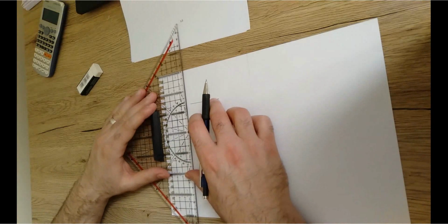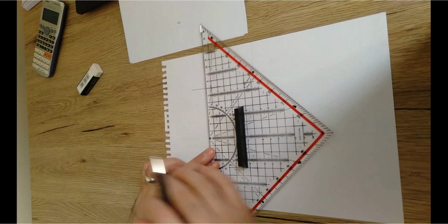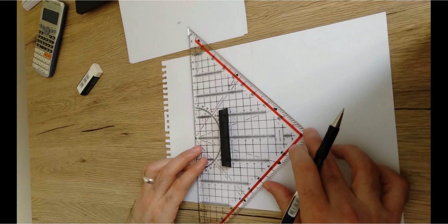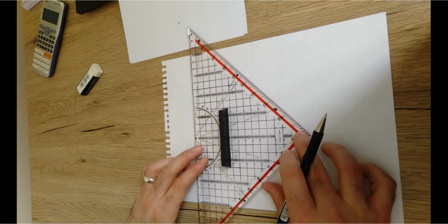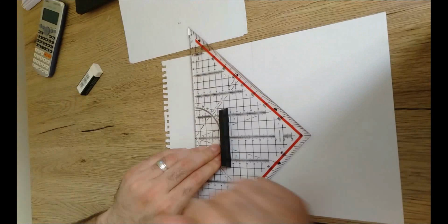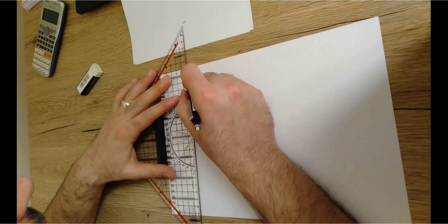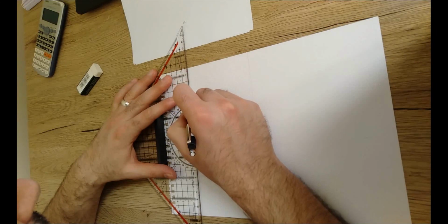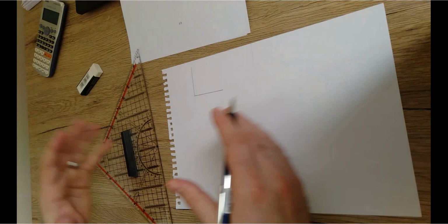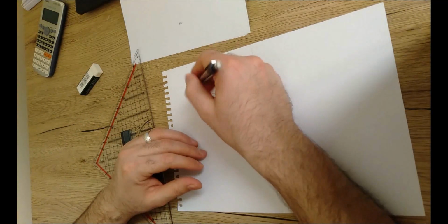Then I'm going to have the second line. I'm going to align this horizontal line to the horizontal baseline that I drew in the beginning, because I need a vertical line, right? From this point, I'm going to drop a vertical line, which should be very light in the beginning. You can also go over it a little to make it clearer so you can see what I'm doing. So these are the two lines forming the angle, and I should set up a curve that is tangent to both of them.